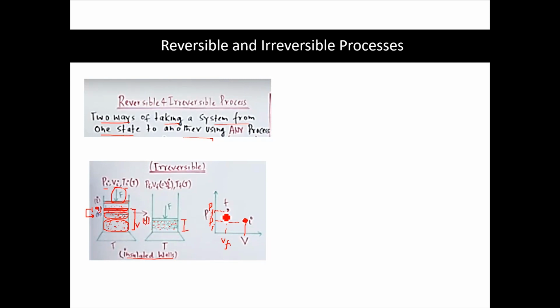In other words, let's say for this volume V, when my system is at state A, volume V, it is some volume over here which corresponds to state A. But since the system was moving so fast, I cannot say whether my pressure in the system was this pressure, this pressure, this pressure. I cannot represent the process on the diagram as my system was not having a uniform single pressure. There was a pressure distribution within the system, and since there is a pressure distribution within the system, you cannot say that your system is in equilibrium.